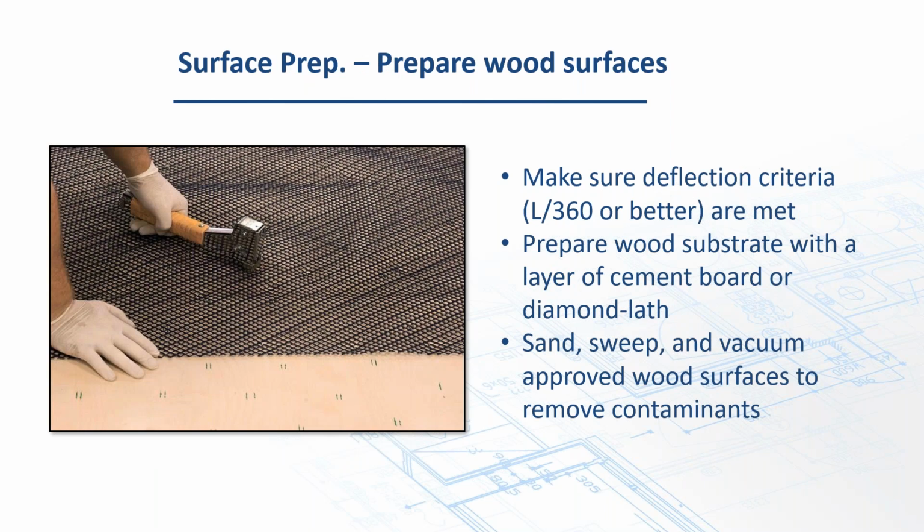Metal lath, depending on the leveler, the manufacturer, they may require metal lath or plastic lath for that matter on all wood substrates. We don't require it. There are substrates, if they're in good condition, that you put a leveler on, a wood one, I mean, and with a good primer, you'll bond extremely well. We've got directions specifically for that. But other people do want a mechanical layer, meaning like metal lath or something like that down.